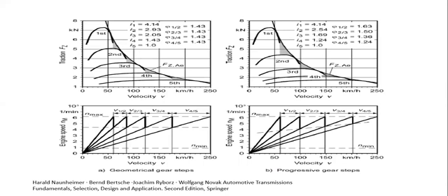For example, if you consider a 5-speed or 10-speed automatic transmission, the gear step from 1 to 2 is equal to the gear step of 2 to 3, which is equal to 3 to 4 and 4 to 5, and so on. If it is a 10-gear, 1 to 2 will be equal to 2 to 3, equal to 8 to 9 and 9 to 10. This is the sequence that a geometrical gear step follows.